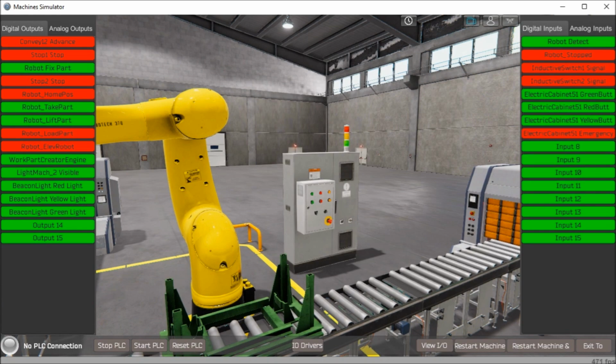Now, here is the sequence table for the robotic cell. If the input conditions are met, then the outputs are set. The next input conditions are looked at, and if they're equal, then the next outputs are set. This will continuously cycle through the table. Now remember, a PLC programmer must know everything about the sequence and operation of the machine before programming. So ask questions or view existing documentation to ensure that you know the logical steps of the machine operation.